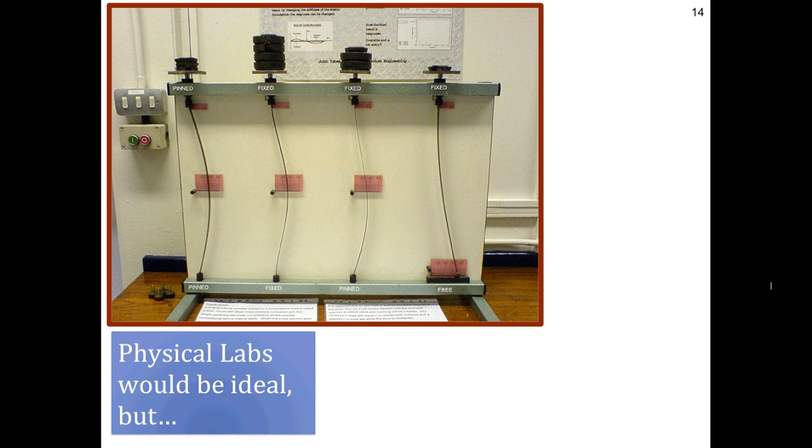Now, it would be great if AISC could send, we estimate that there's a little over 1,000 of you watching the show tonight, each one of you one of these little devices. They're quite clever, and what we're seeing here is within the body of the device there are a whole bunch of columns, 4 columns. The difference between the 4 columns is the end restraint. The first one is pin-pin, that was Euler. Then we have a fixed-fixed column, fixed-pin, and fixed at the top, free at the bottom. And then what you would do if you had this device in front of you is you'd start stacking weight to find out how much load it takes to buckle the column. And physically you would see the column buckle, and on top of it you'd see the amount of weight that it's holding when it buckled, and you could compare the performance of these columns. And the only thing you're changing is the amount of restraint at the ends, the support conditions. So that would be great.